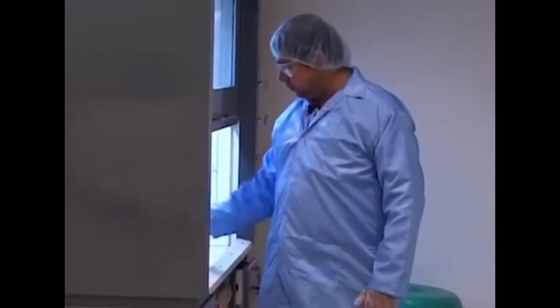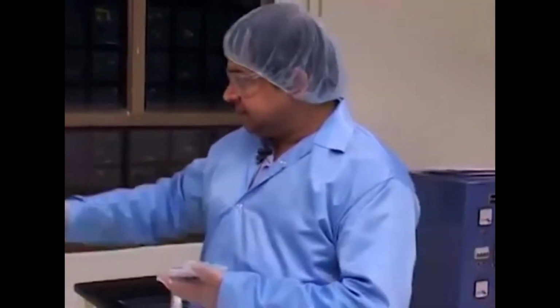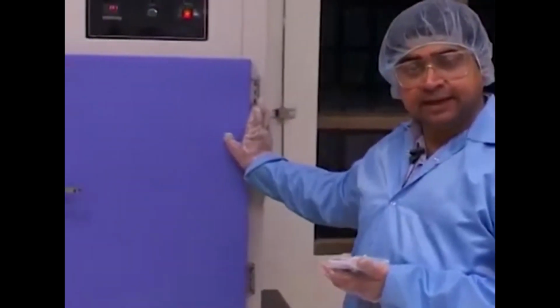So basically what we do now is to take this wafer that we just made super clean using Piranha process and take it to an oven. The oven basically that we are using here is a gravity fed convection oven, which actually is based on the principle of free convection. There are a set of heater coils at the bottom, and there is a current of air, heated air, which actually makes the temperature uniform. There is a PID based controller using thermocouple, which is somewhere at the floor of this particular heater. This right here is that oven.